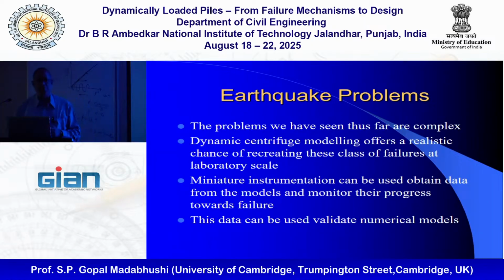One of the big advantages of centrifuge testing is that we can put instruments in and see what is happening before, during, and after the earthquake, which means we can track the movement of the structure towards failure. You can also use this data to validate numerical models. So you have quite a lot of advantages.